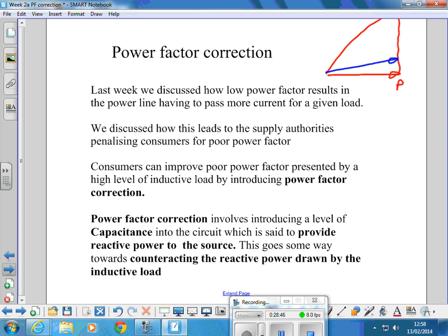What happens in the generally found parallel circuit if you achieve resonance is you get circulating currents that go around the parallel paths that aren't actually coming in through from the source. And these are the high currents generated by the inductor. Okay? So you do not want that at all, particularly in a high current, high voltage mains system situation like